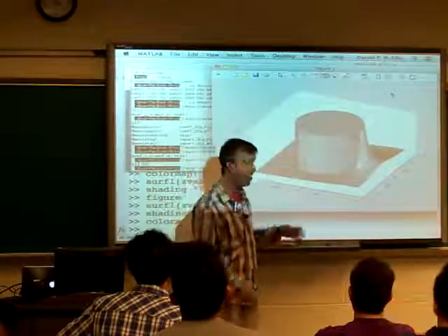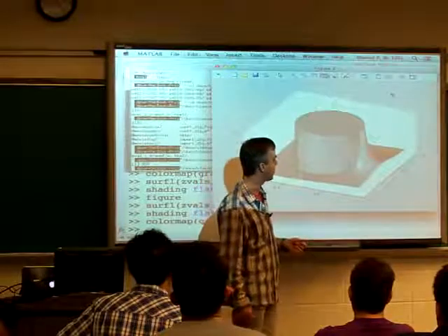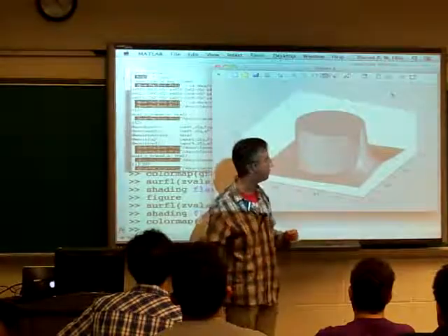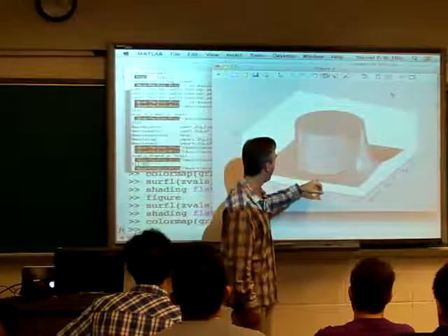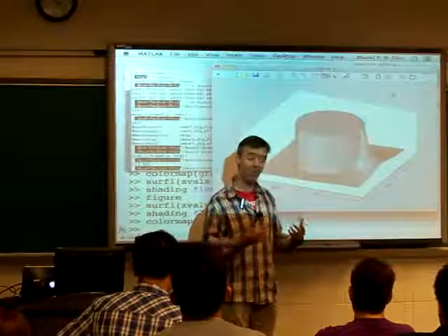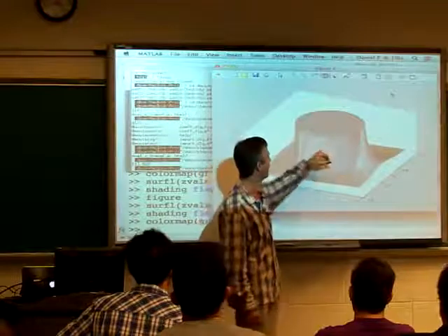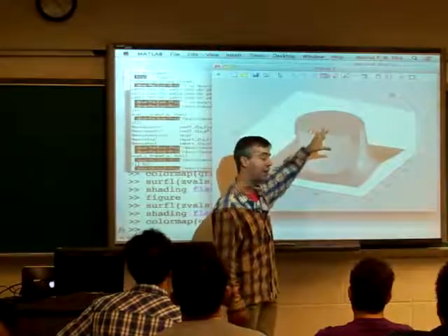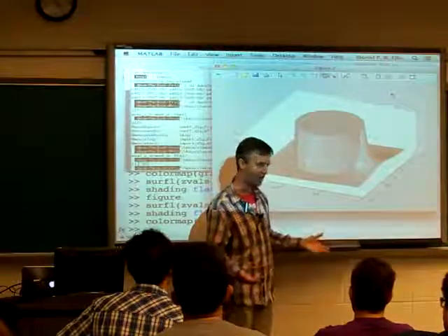And so we typically observe this with many z transforms, particularly for infinite length sequences. And so we call this range of values of z for which the value of g of z converges the region of convergence. And this range of values in here, where when we try and evaluate g of z, it blows up, that's not the region of convergence.